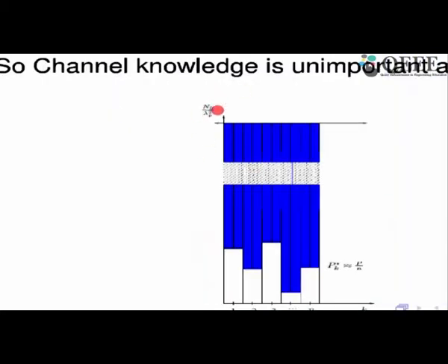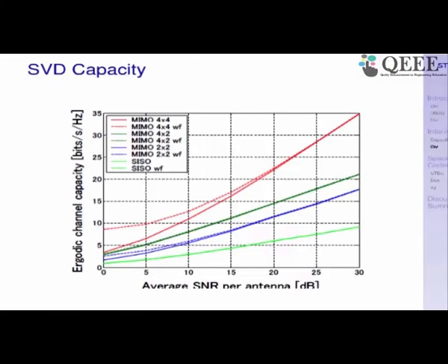So these are the n naught by lambda square. These are going to be very small compared to the power. So this gap means it is large. The power is very large compared to these values, the second term in the optimal P derivation. So if they are very small, they are almost all equal to P by n. So it is as if you are equally dividing power among all of them. This scheme that we have defined just previously is also called the SVD MIMO. It is a capacity achieving scheme.